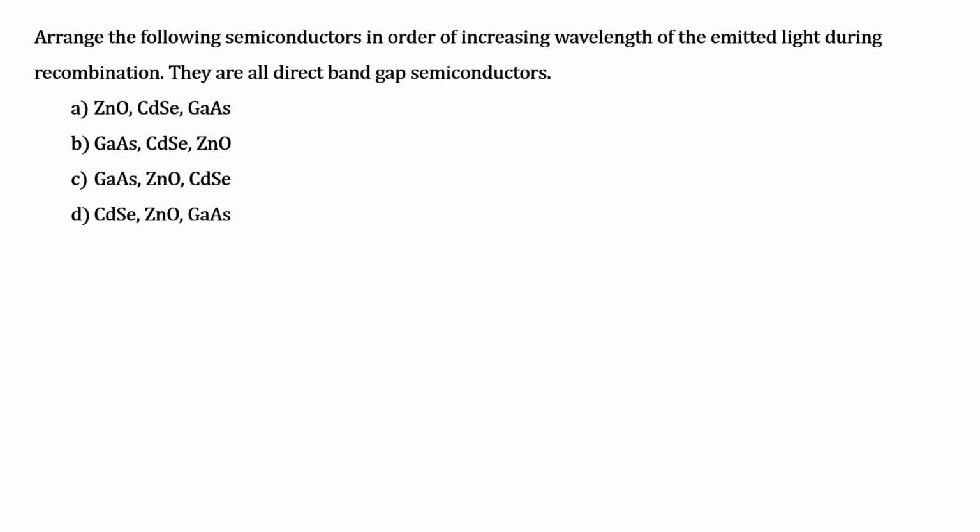Yes, ma'am. Next, arrange the following semiconductors in the order of increasing wavelength of emitted light during recombination. They are all direct band gap semiconductors. The same logic applies: based on the band gap, lambda has an inverse relation with it.